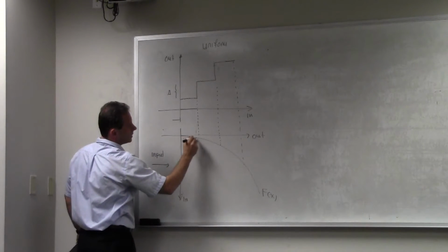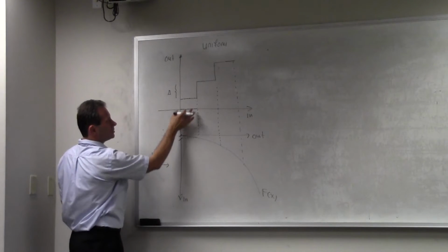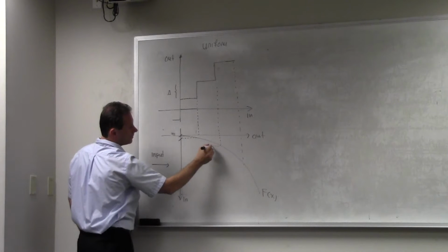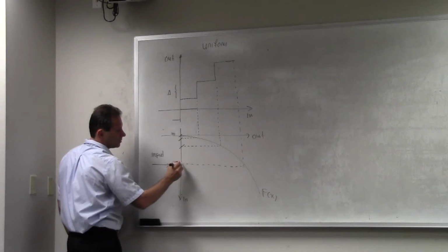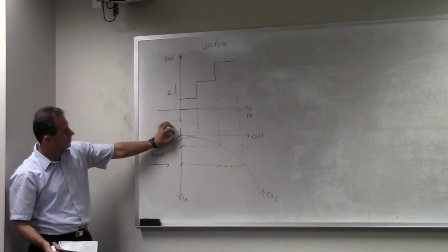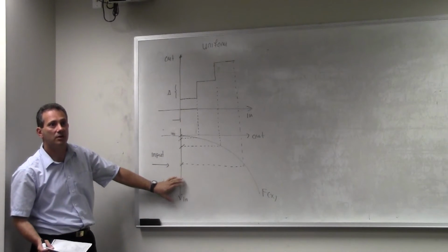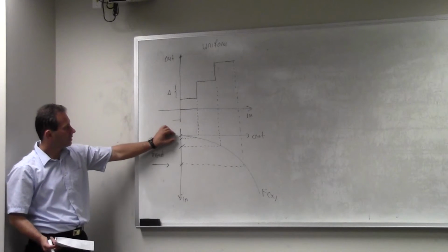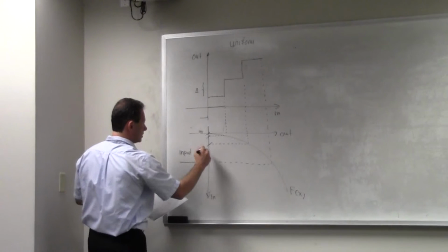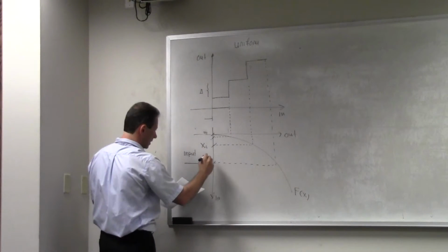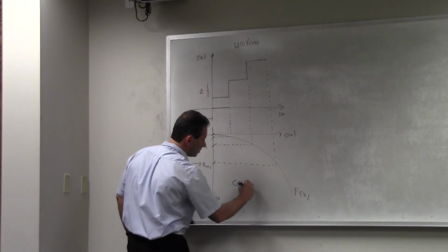The first interval is this large. So what is the first interval? From here to here, because this small interval now is going to be mapped into this quantization level. If you look at the second one, look how large the second interval is. It's slightly larger, and then everything that falls within this interval is going to be quantized as a third level. So you can see now from the input standpoint, these quantization steps grow. They are very fine in this area, and they become progressively larger as you move to the higher amplitudes. So the quantization is finer here and coarser towards the end. Let's call this level here x i plus 1, and this is your input that comes into this. So this amplifier we're going to call the compressor.